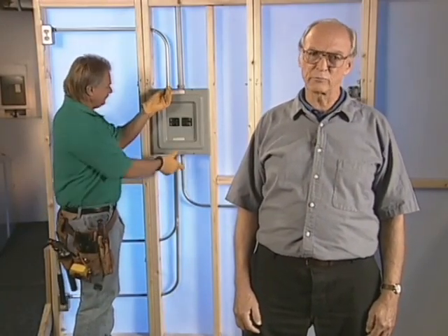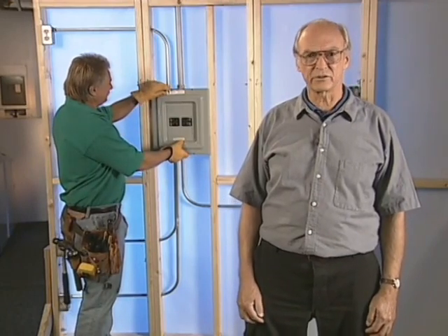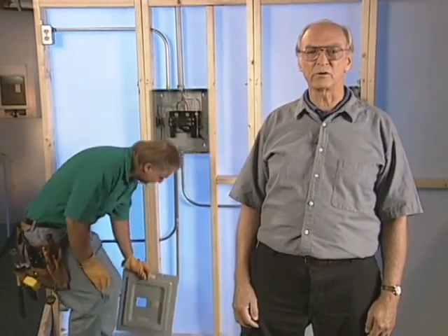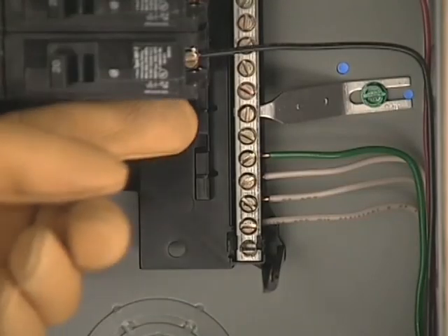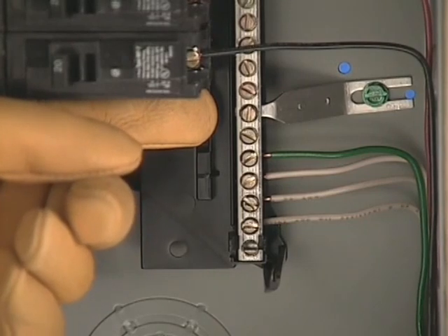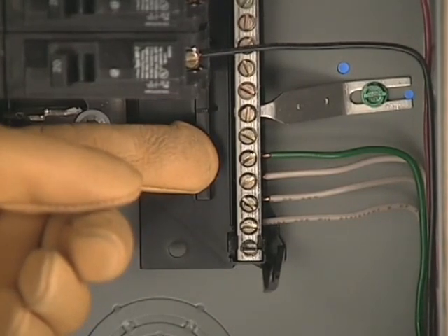There are three fundamental ways neutral gets on grounding conductors. We'll illustrate the main one on our demonstration subpanel. The first is when a neutral bus is bonded to the subpanel, or there are equipment grounds connected to the neutral bus. Here we're using a simplified demonstration panel to illustrate various misconnections. The consequences of this situation are currents on various metallic structures in the building, as well as a net current on the panel feed all the way back to the service entrance point.